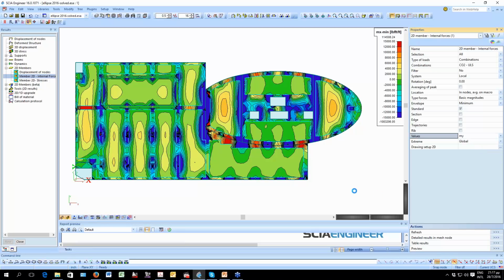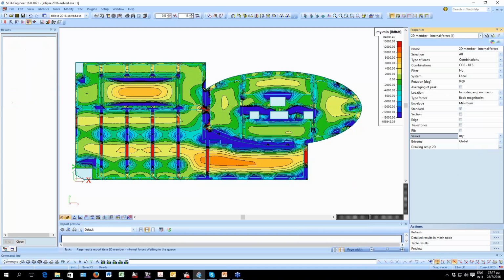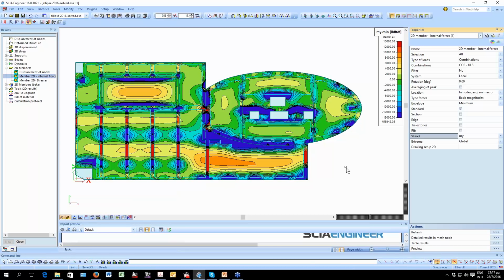In the same way, you can see the rebar contours. You can do the design of the slabs. Obviously, you could model the ribbed slab as a flange with ribs, but this would not be cost effective for a 45-story building. You can do that for only one story and then extrapolate the results for the remaining stories as far as the slab is concerned.